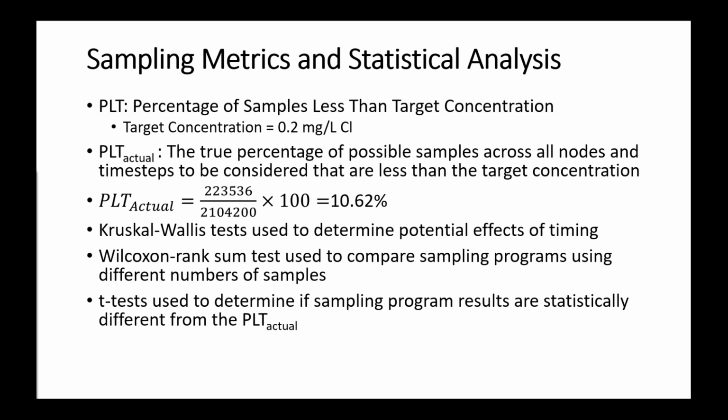I then use a number of statistical tests. The purpose of these tests is to see differences between different timings, differences between numbers of samples that are collected, and ultimately to compare what we actually measure for the PLT, the percentage of samples less than the target, that we observe from the sampling program results, compared to what the true PLT condition in the network is.